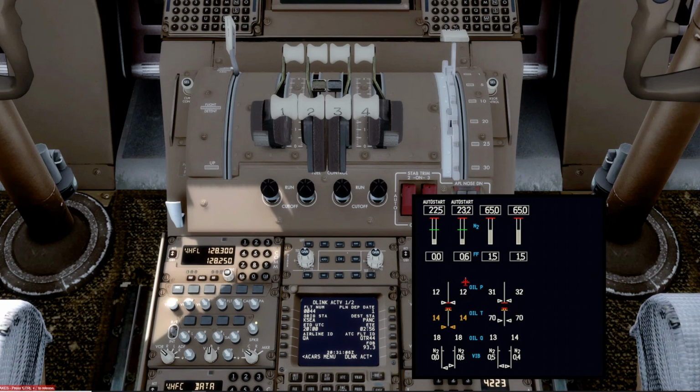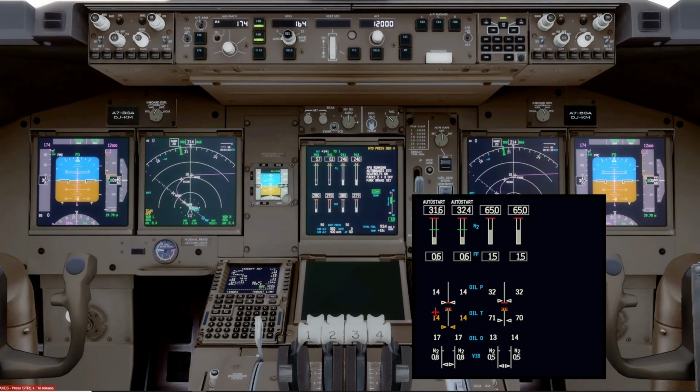You'll notice eventually fuel flow will be introduced, and then we'll get light off with the EGT, which you've got already. You can still monitor all this, but we're not going to take action on anything unless we get an ICAS message telling us to. This message is normal right now for when you start the number 4 engine, so we'll cancel that.